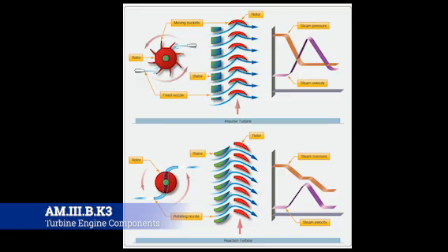All right, now the turbine nozzle guide vanes can usually be adjusted during engine overhaul and assembly in order to increase the efficiency of the airstream striking the blades or buckets of the turbine. So you'll go through there and make sure that they're all turned right, because over time things will move and shift and corrode and cause problems. And so whenever you're overhauling, you're trying to reset it and you'll get a lot of power back that you had lost over time.